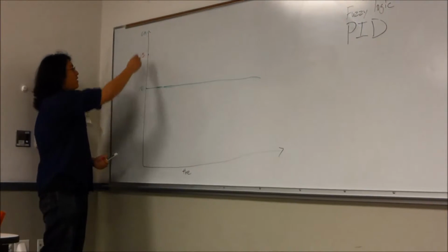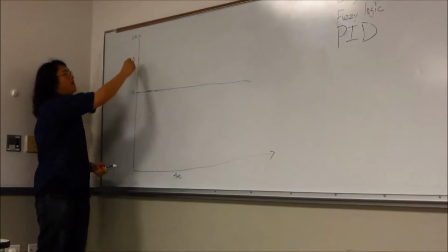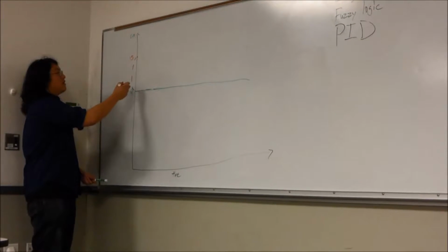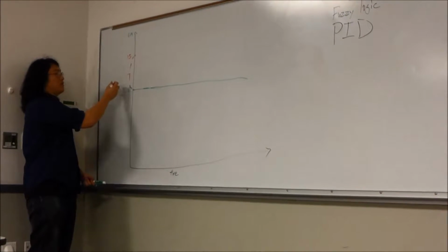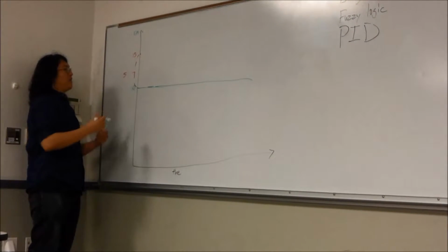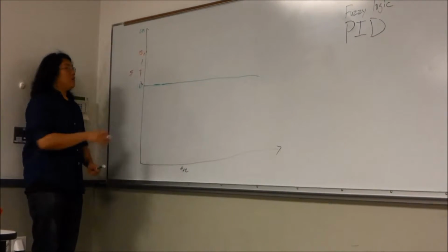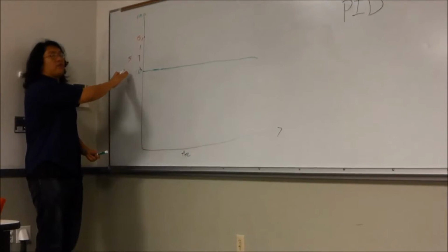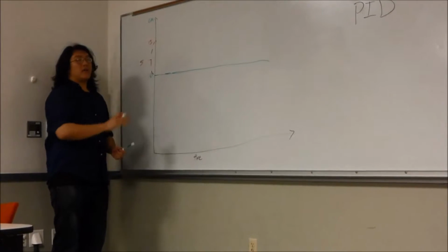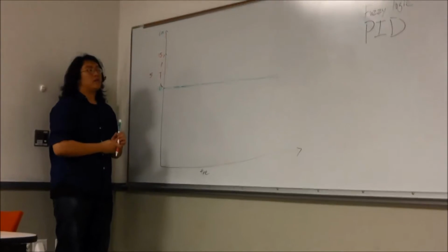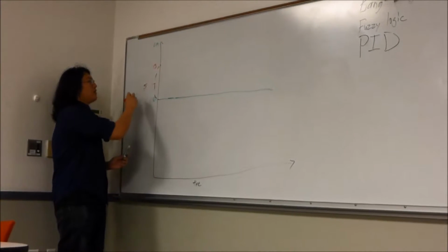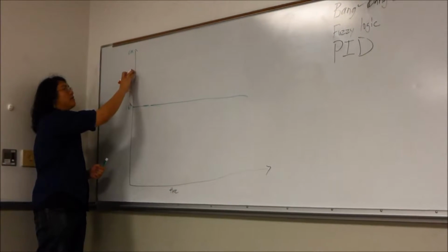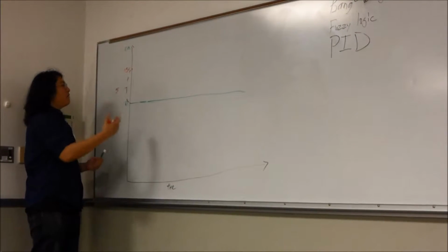So let's say I am 5 centimeters away from my target. This yields 5 centimeters of error. We can move proportionally, which is the P in PID, to this 5 centimeters of error, whereas we say we're going to output more motor power depending on how big the difference is between our desired value and our actual, red data point.